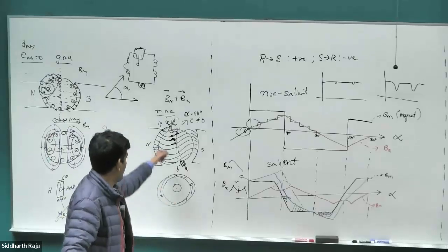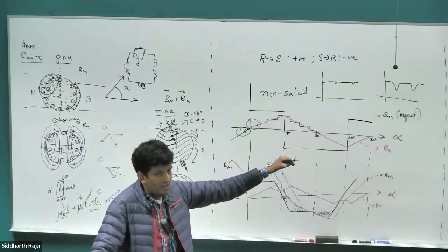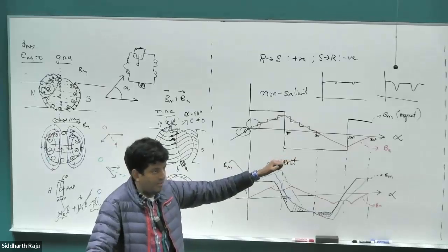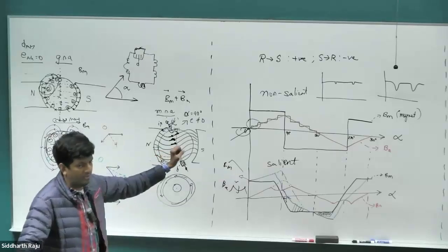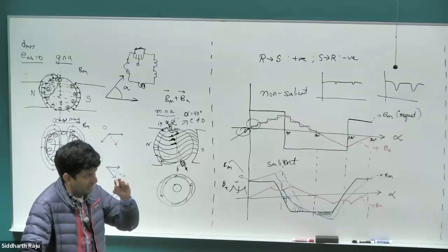We saw one method is shifting the brushes, right? But shifting the brushes has its own problem, it creates the direct demagnetization effect that we just saw. So that is to be avoided as much as possible, especially in very high power motors. In low power motors, it's absolutely fine. Even in the lab motor, you'll see the brush is slightly shifted off axis.